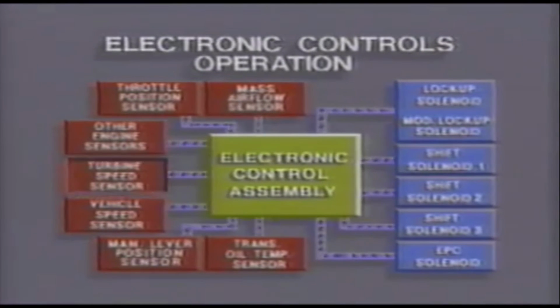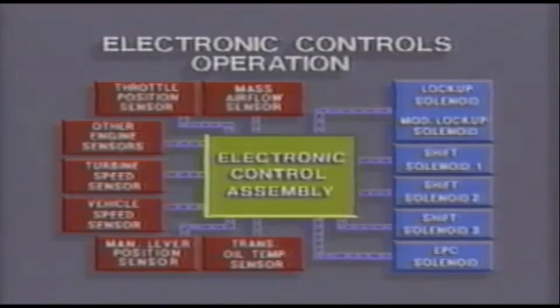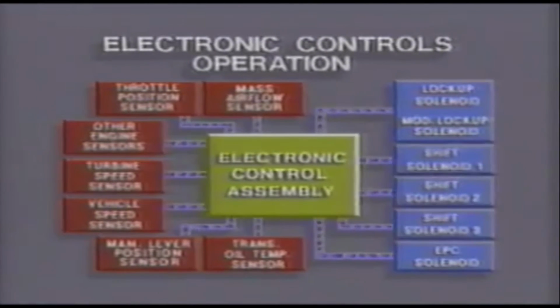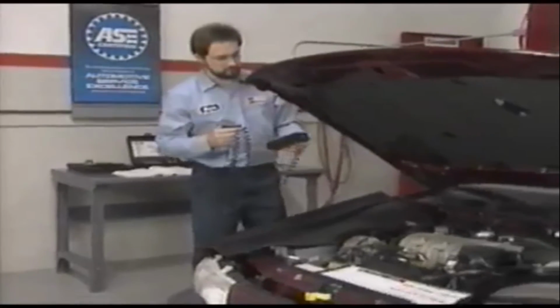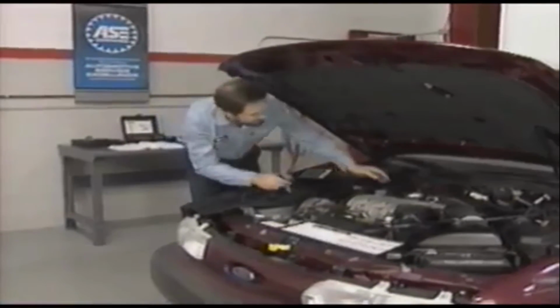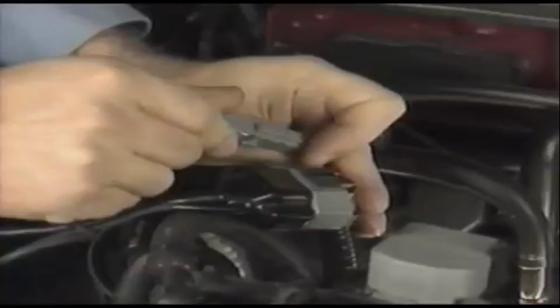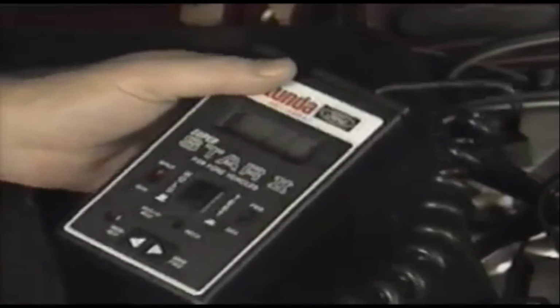Input devices, located at various locations, are constantly monitored by the processor, an electronic control unit that then controls the ground for the output devices that are usually variable force or on-off type solenoids. To help you in diagnostic routines, electronic control systems can also record occurrences of input failures for later retrieval during self-tests.